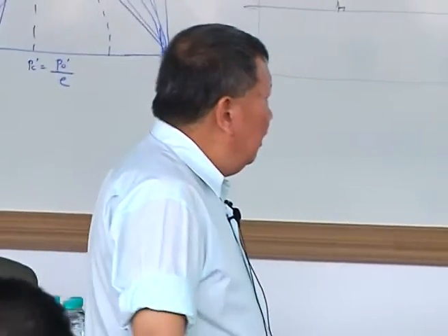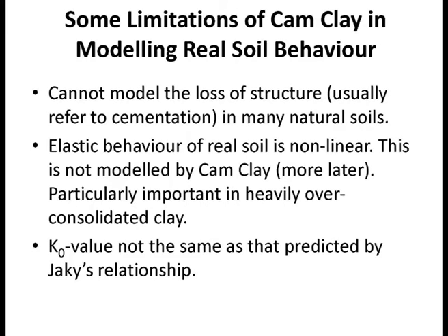Now, we have just covered the modified Cam clay this morning, and I want to say something about limitations of Cam clay in modeling real soil behavior. As I mentioned to you, there's no such thing as a model that will 100% model real soil behavior. Even something as simple as Singapore marine clay, the behavior is actually quite complicated. And I'm going to show you some test results and what are the problems of modeling that behavior. Okay, some of the limitations. This is not an exhaustive list, but I think it basically shows you some of the main problems.